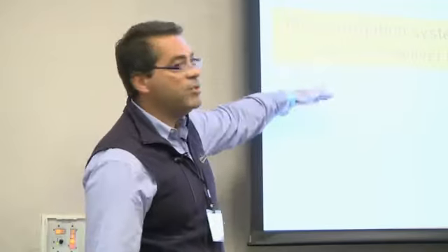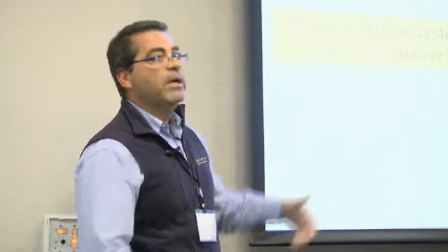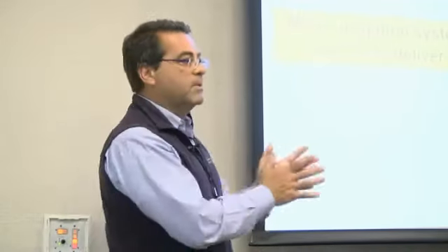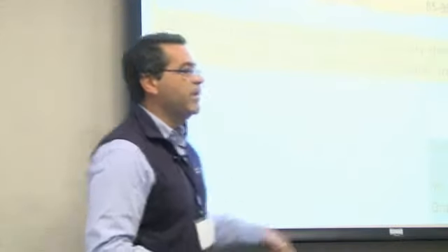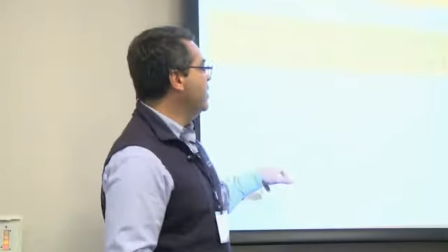So you have inches here and inches per hour here, and at the end you have the maximum time of irrigation. What I should really point out is that I want to make sure that you design your application rate in a way that is lower than the soil infiltration rate.